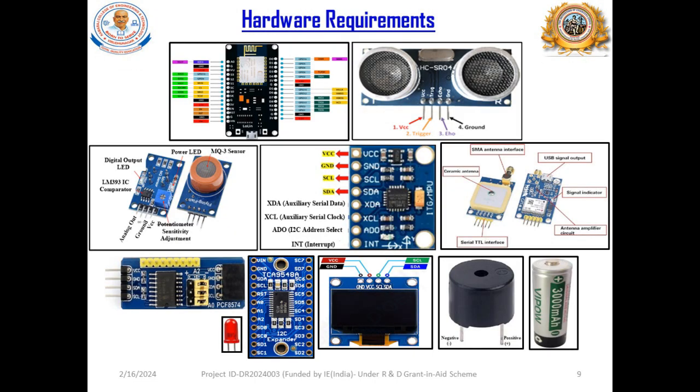These are the hardware requirements. The first one is the NodeMCU ESP8266. It has 30 pins, including the GPIO pins, I2C interfaces, UART pins, PWM signals, as well as the power supplies. It has a 5 volt power supply as well as a 3.3 volt supply.